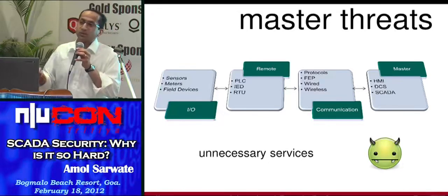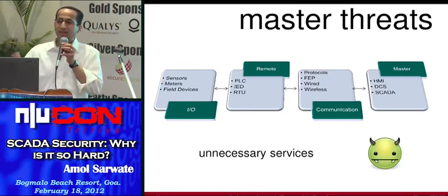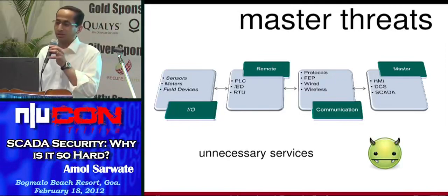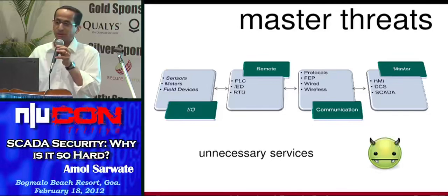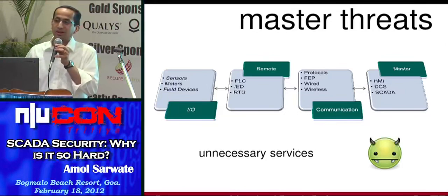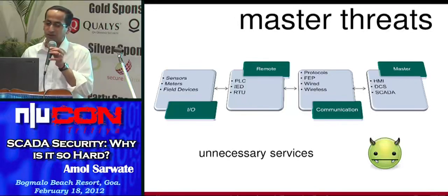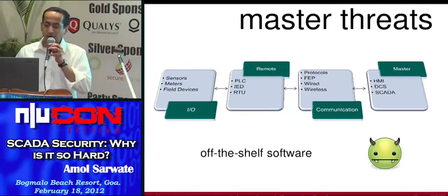Since, as we mentioned, a lot of SCADA systems are Windows systems, all the regular IT-based challenges are now here. There are a lot of unnecessary services running. It's no longer a proprietary system; this is a Windows-based system. So you will have unnecessary services, and you will have to take care of hardening of the OS and do a lot of these things because of the off-the-shelf software.